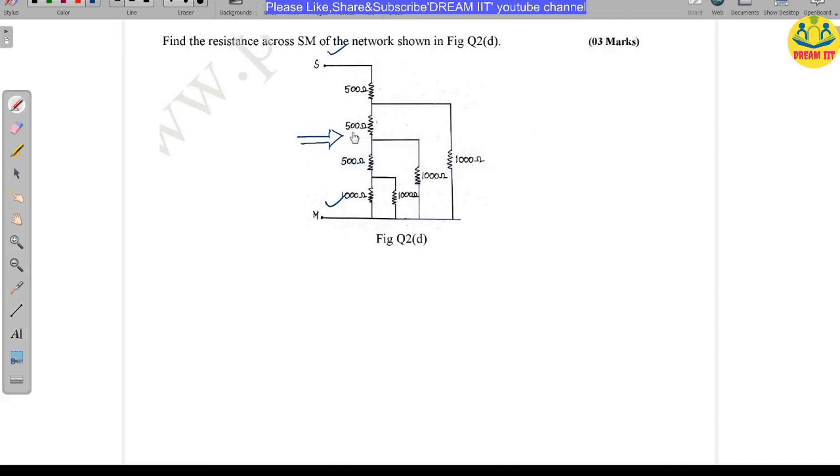See this 1000 ohms and this 1000 ohms, they both are in parallel, so I am going to reduce them first. 1000 in parallel with 1000, divided by 2000 as they both are adding. The 3 zeros get cancelled, and you are going to get 500. So it is 500 total after reduction, so you are getting one reduced circuit with 500 ohms.